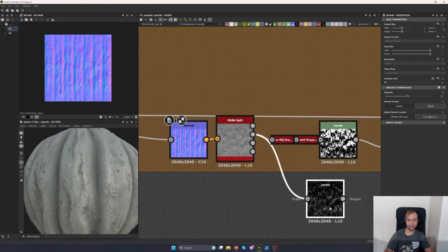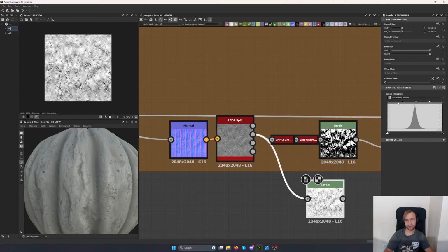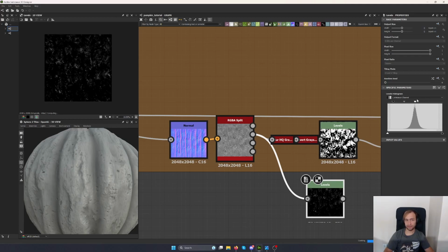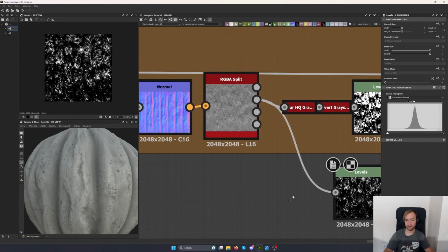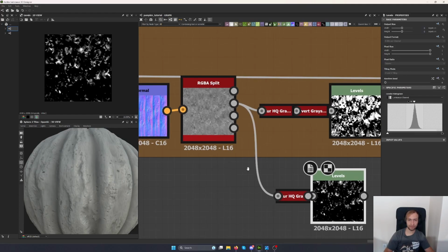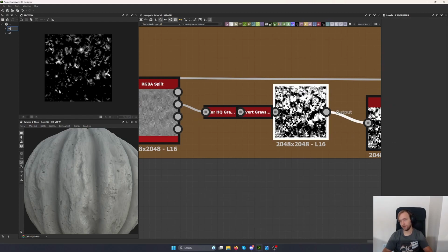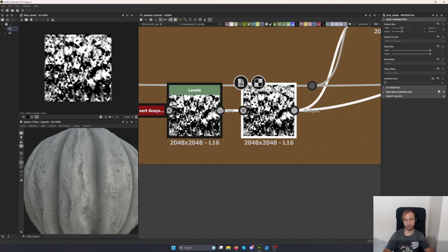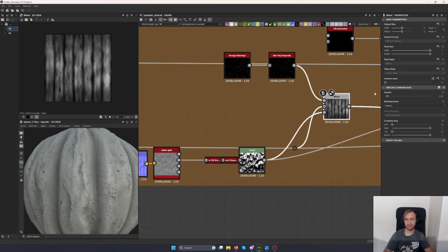Your up will be different. In our case, we have to flip it. And here we are just picking out our up-facing shapes, and to make that smoother and not have that many lone pixels, we just blur it. So that's what we have here. Then on auto levels that isn't really needed, so I just remove it, and this is our mask here.